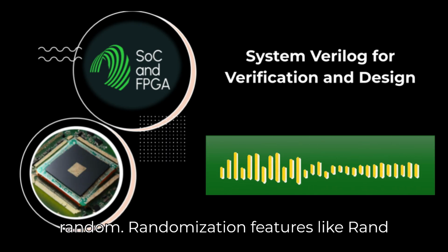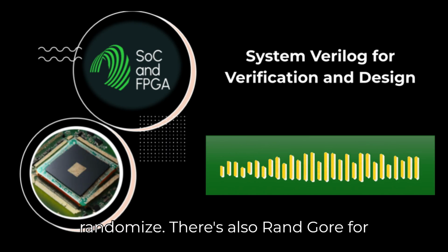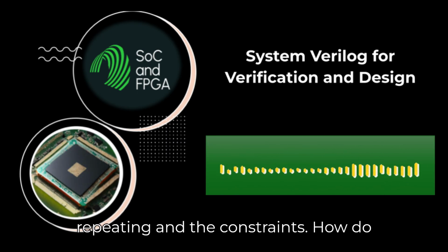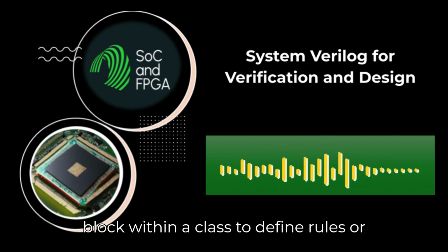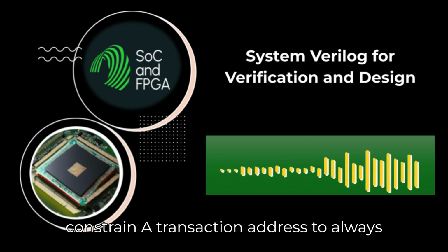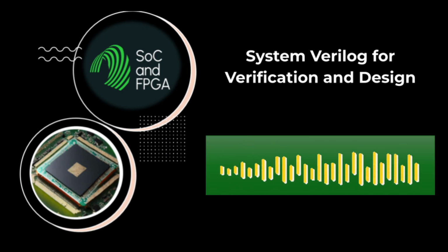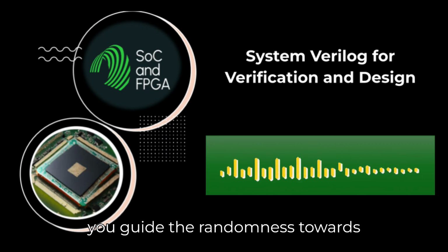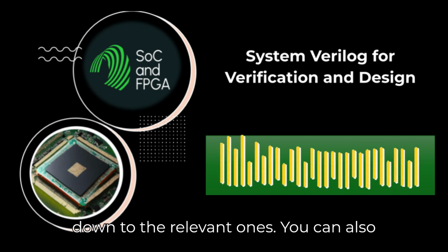You use randomization features like rand variables in classes, which get assigned random values when you call object.randomize. Yeah. There's also randc for cyclic random variables. They cycle through all possible values before repeating. And the constraints, how do they work? You use the constraint keyword block within a class to define rules or relationships between the random variables. For example, you could constrain a transaction address to always be within a valid memory range, or ensure that the packet size is always non-zero. You use the with keyword with randomize sometimes, too, for inline constraints. So you guide the randomness towards interesting or legal scenarios. Exactly. You prune the vast space of possibilities down to the relevant ones.